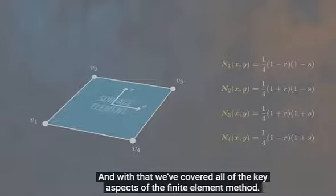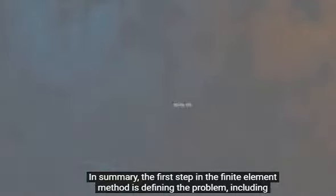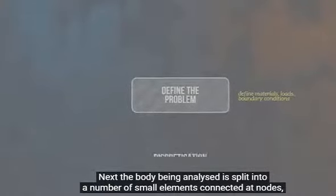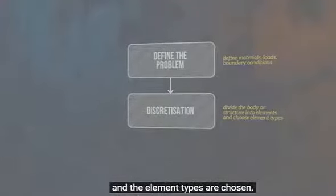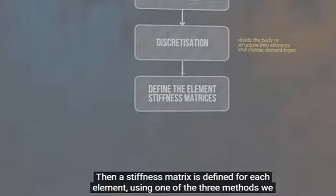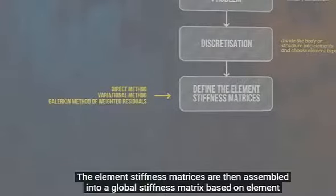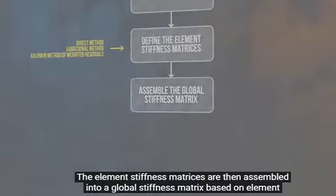And with that, we've covered all of the key aspects of the finite element method. In summary, the first step in the finite element method is defining the problem, including the relevant material properties, loads, and boundary conditions. Next, the body being analyzed is split into a number of small elements connected at nodes, and the element types are chosen. Then, a stiffness matrix is defined for each element, using one of the three methods we covered earlier. The element stiffness matrices are then assembled into a global stiffness matrix based on element connectivity.